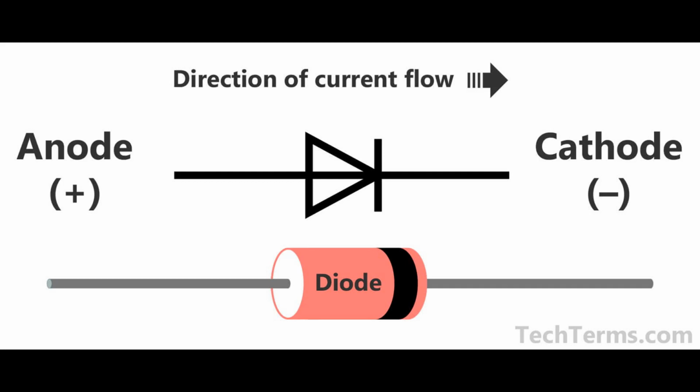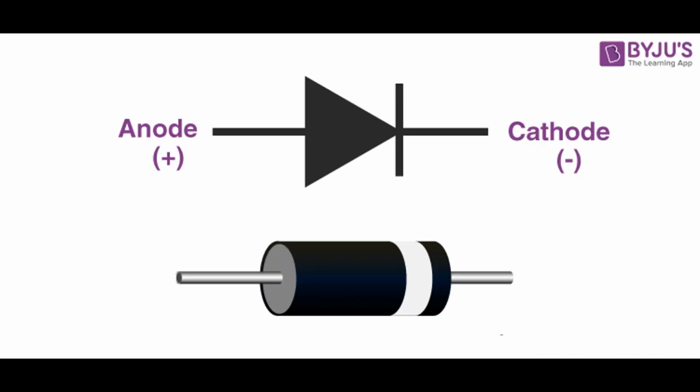Due to its simplicity, the half-wave rectifier is sometimes used in applications where a low-cost solution is acceptable, and the disadvantages mentioned above are not critical. However, for most practical purposes, a full-wave rectifier, using a bridge rectifier circuit, is preferred, as it provides a more stable and efficient DC output by utilizing both halves of the AC waveform.